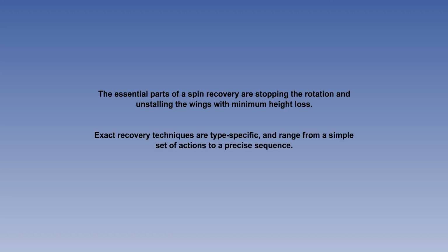The recommended recovery for some types involves simply reducing power to idle and centralizing all flying controls or relaxing any pressure applied to them. At the other extreme, some designs dictate that a precise set or sequence of control movements is carried out, timed to coincide with certain points in the rotation and for several turns.